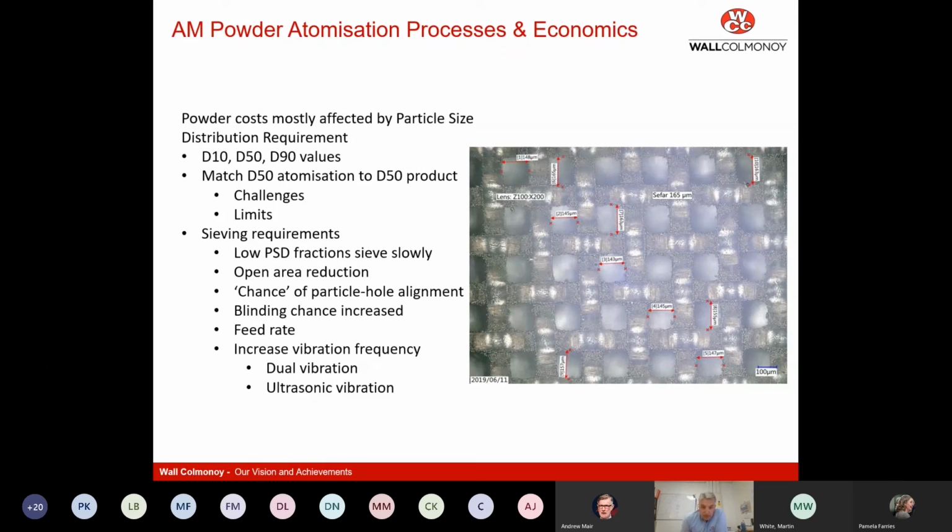It does provide challenges. The image on the right is a blown up version of a nylon screen. So you can see that there are holes there that the powder particles have to fit through. The screens you can see here are about 150 micron screens with some variation in some of the sizes. So they range from 145 to maybe 163. And this is a well-known manufacturer of screens.